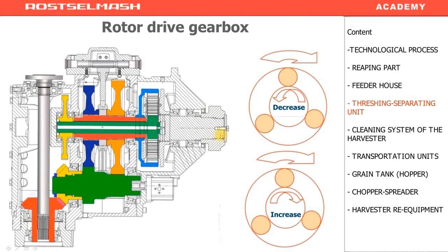With the help of this planet gear, you change the rotor RPM in the selected range, the first or the second one. If you block the gear, the satellites will be rotating around it with one steady speed, depending on the speed of the crown. The faster the speed of the crown, the faster the satellites rotate, and so the rotor will rotate faster as well. When you have selected the second range, it becomes constant, and the gear does not change its diameter. So in this case, the crown speed will be constant. In the second range, it'll be 750 RPM.